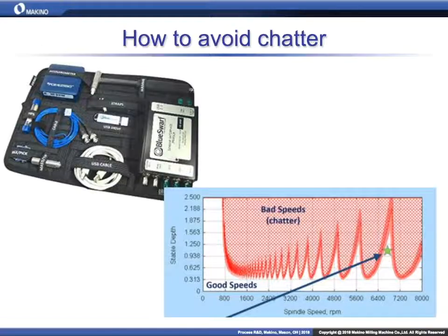I find there's actually a lot of interesting information in these for those who haven't seen this before. I would have thought it should be called the instability lobe diagram because the red part, the lobes, are the unstable area. But you notice as you get into higher RPMs, these sections of stability get bigger and bigger. So with higher RPM machines, this is really valuable when you're cutting aluminum at higher RPMs. You can find a great RPM and a great axial depth.